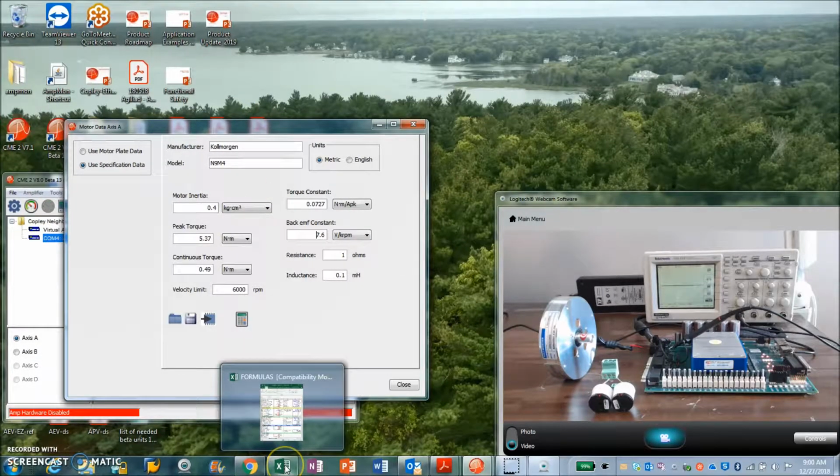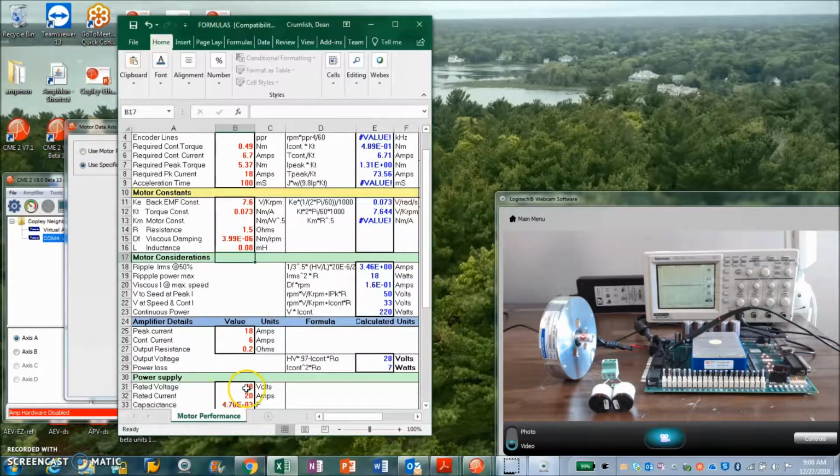And let's take a quick peek at that here too. So I used a 48 volt supply, added up the resistance. I'm going to say 80 microhenry because that's what we measured with the inductance meter. That's a ripple lost watts of 18 watts, which is not bad. It's a little bit more than 10% of the motor's watts. We could probably do this without inductors, except very low inductance can sometimes cause a short circuit. So if we're less than, say, 50 microhenries, that could trigger a short.